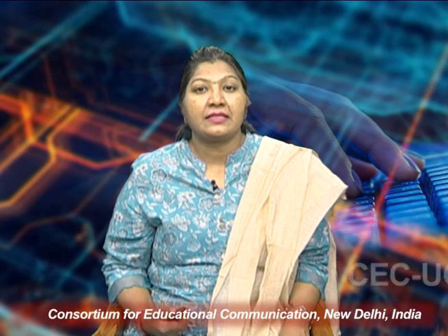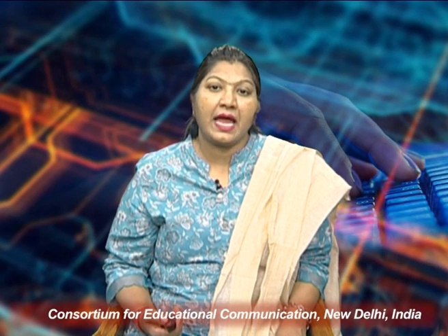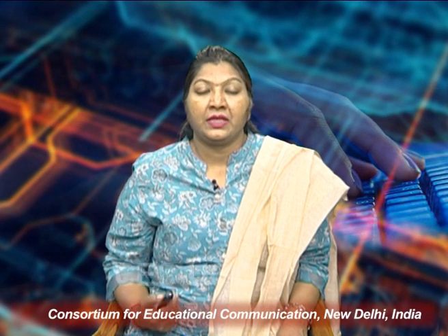This has the effect of increasing the speed of operation of emitter coupled logic gates up to the gigahertz range compared with the standard TTL type. ECL logic uses unsaturated transistors that operate within their active region and amplify as well as switch signals. So these are the ECL family.